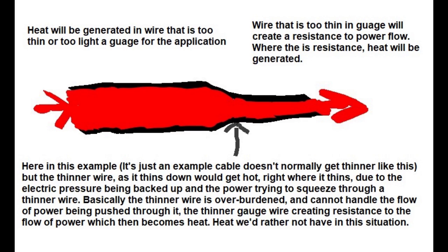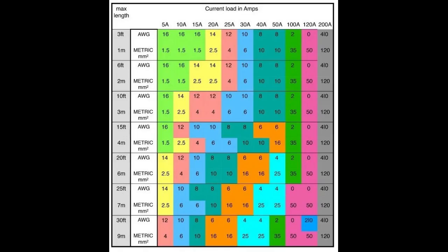I won't get into the fact that if a wire is too thin, the wire will also warm up, the heat in itself gobbling up some of the electricity, not to mention the possible fire hazard. But the voltage will also be affected and reduced, hence the wattage diminishing, or power in general diminishing. It's not just the gauge of the DC wire being too thin for an application, it's also the length of the wire can also be too long. In DC electricity, it is very important to get the gauge of the wire correct, based on the length and power demands being made on it.